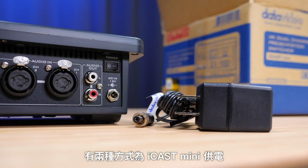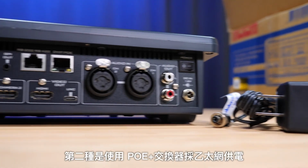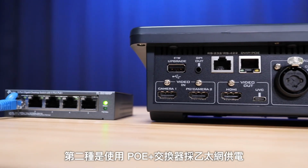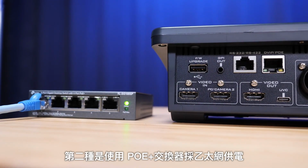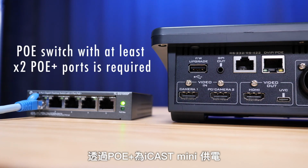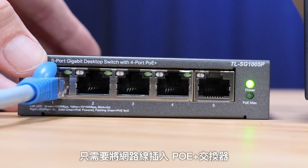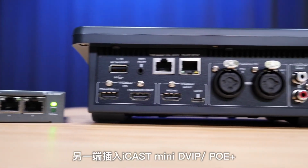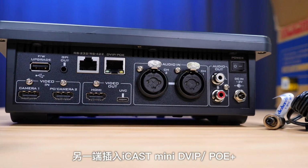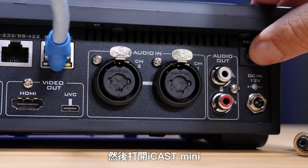There are two options for powering the iCAST Mini. The first option is using the included 12-volt power supply. And the second option is to power the iCAST Mini over power over Ethernet, using a simple PoE plus switch right here. To power the iCAST Mini over PoE plus, simply plug in an Ethernet cable into your PoE plus switch, and then in the iCAST Mini's DVIP/PoE plus port, plug in and turn on the iCAST Mini.